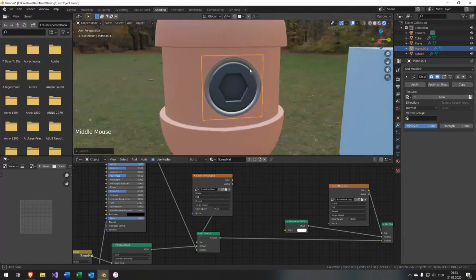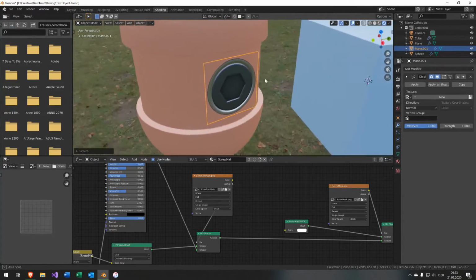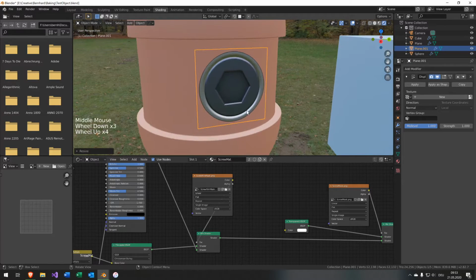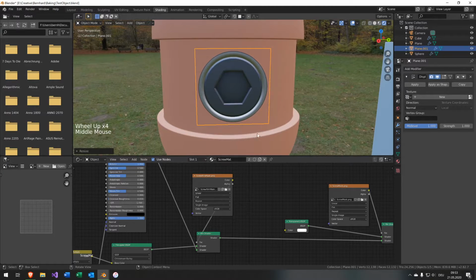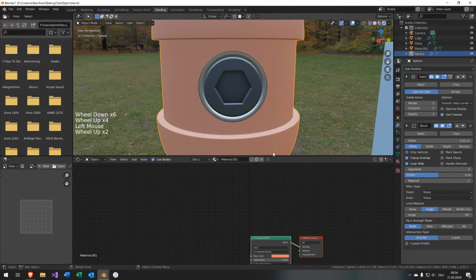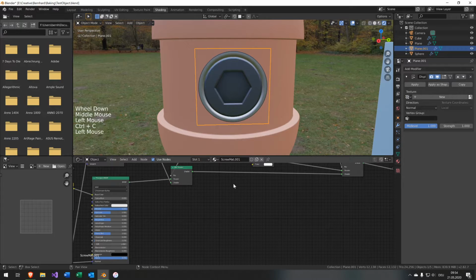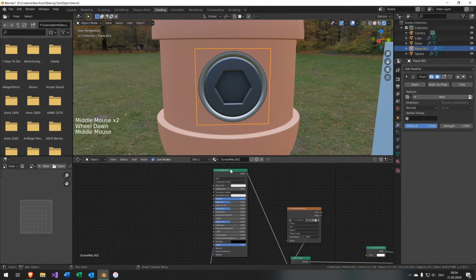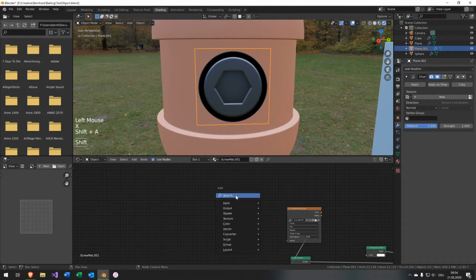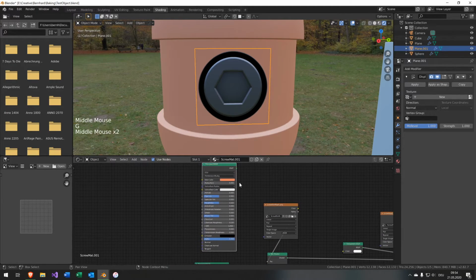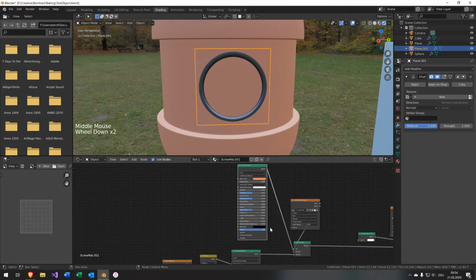So now I've duplicated it and moved it to our cylindrical object, and I'm already seeing that it's a flat plane that is aligned on some sort of tangent point, but is not wrapping to the surface. The first thing I'm going to do is replace the material for the rim. So I'm deleting the original BSDF here and pasting in the BSDF from our surrounding materials, so from the cylindrical object. I'm going to put it into the input here and connect the normal.